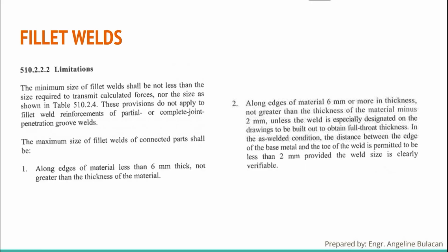So let's say for example, yung base plate mo is 10 mm. So pinag-usapan is yung maximum size ng fillet welds mo. So 10 minus 2, it is equal to 8 mm. So therefore, yung maximum size ng fillet weld mo is 8 mm.